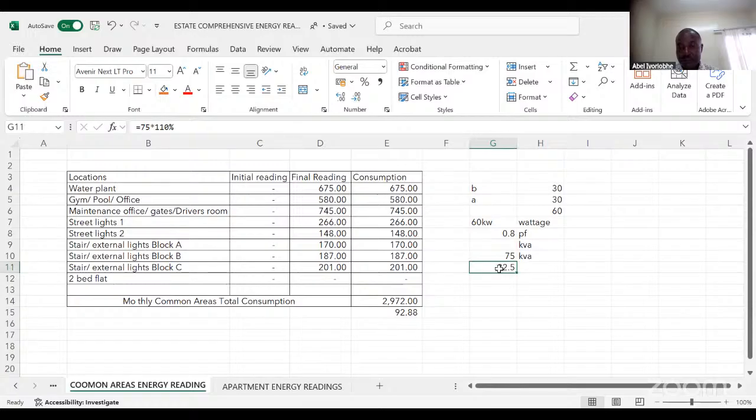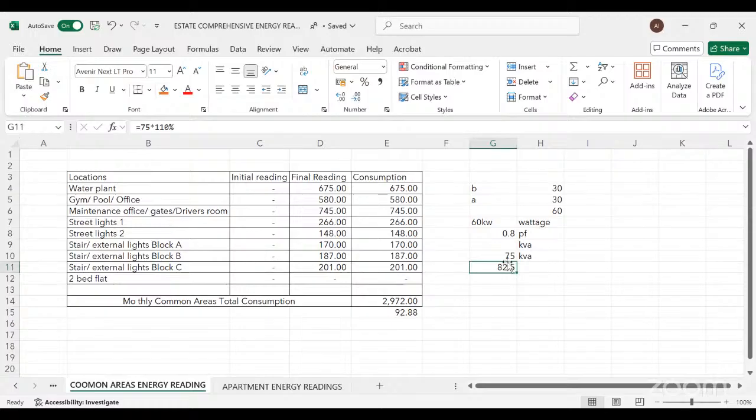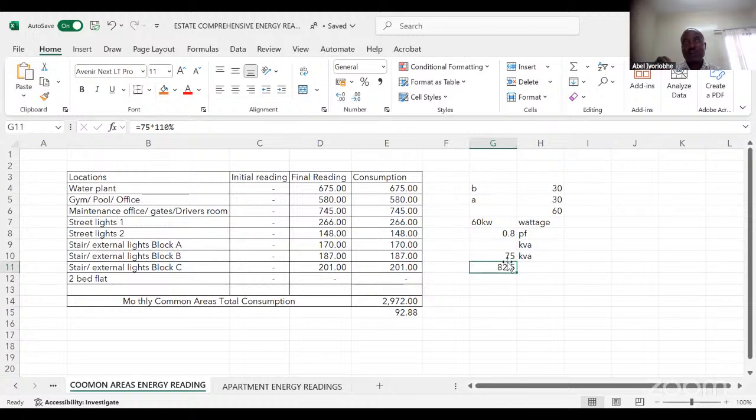Hello? We are with you, sir. Okay, from there, in my explanation, I said we must give room for future expansion. You don't just recommend the very size that you have determined. There may be plus or something in the building. Oh, we need a fridge here. We need something else here. So we will now have to recommend either 80 or 82 kVA to your client. Is that taken?